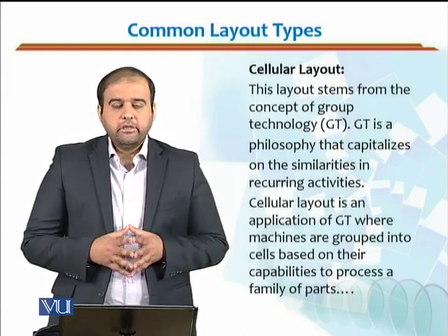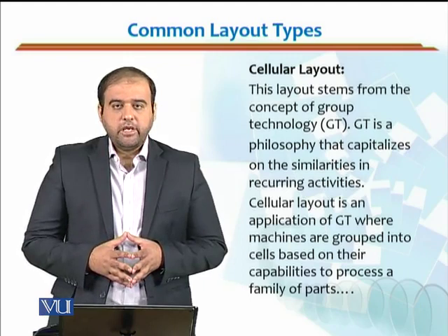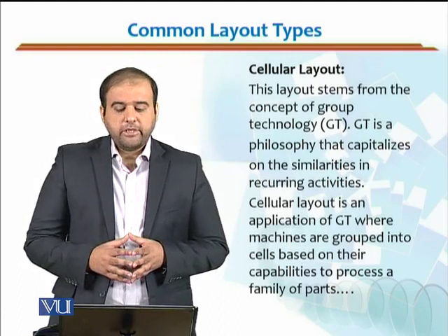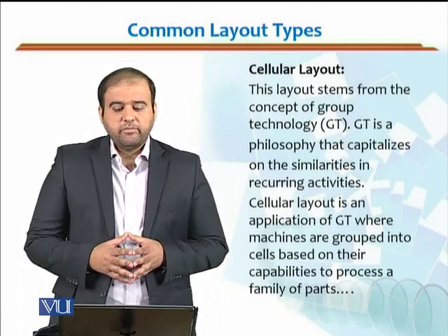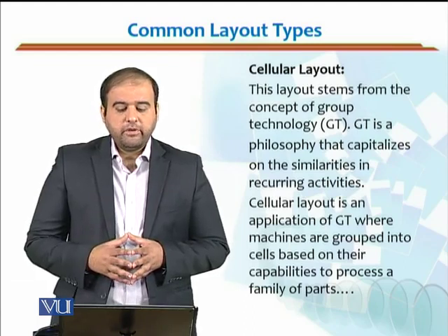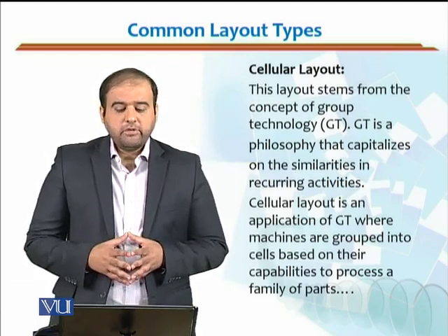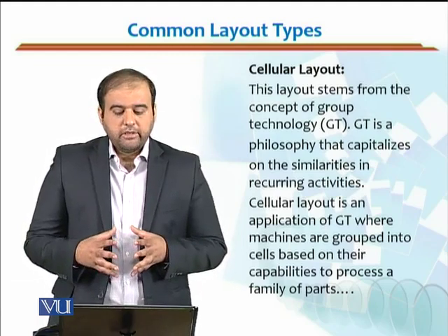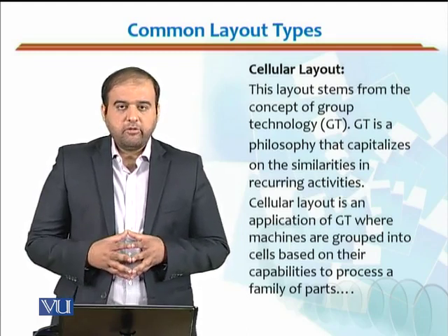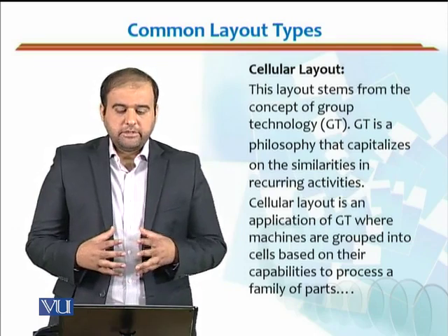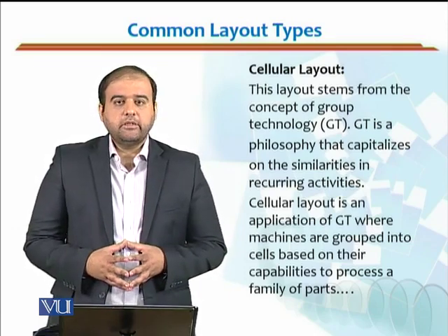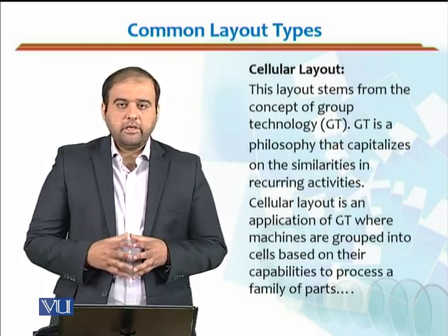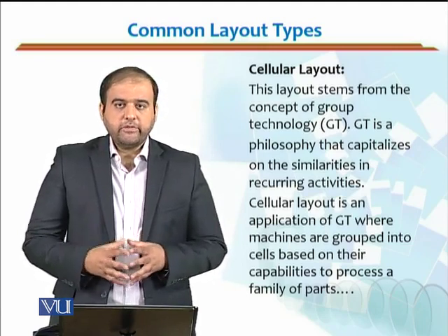Then we have an important type of layout, the cellular layout, also known as group technology. This layout stems from the concept of group technology. GT is a philosophy that capitalizes on the similarity of recurring activities. Cellular layout is an application of GT where machines are grouped in cells based on their capabilities to process a family of parts. So different types of machines could be in a group or a cell, and they would perform the function either sequentially or simultaneously.